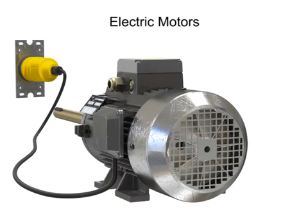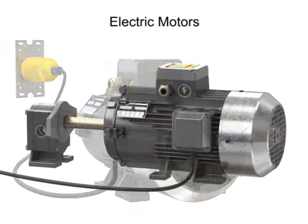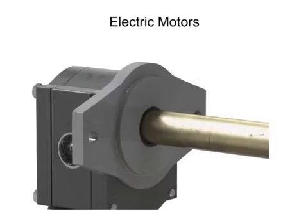Since these multi-directional motors are equally efficient in either direction, there's no standard direction of rotation. Therefore, when a three-phase motor is first connected, it may run in either direction, and technicians must be careful to install it properly. While the motor itself can run in either direction without harm, the components that the motor drives may be unidirectional. For instance, running a pump in the wrong direction may cause damage due to cavitation or expulsion of the shaft seal.